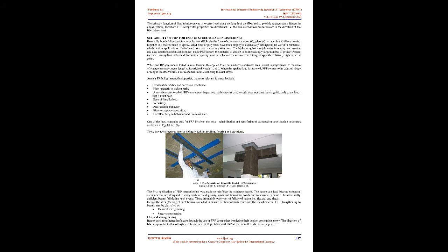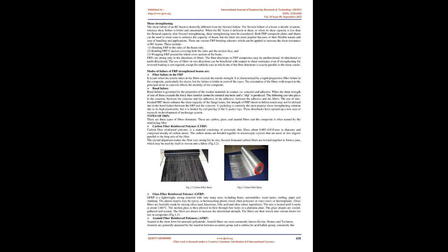Repair and rehabilitation work for concrete structures can broadly be classified into two categories. Repair, in which damage due to deterioration and cracking is corrected to restore the original structural shape, and strengthening, which is necessary to strengthen the structural capacity of members whose load-carrying capacity is either inadequate or whose strength has been severely impaired due to sustained damage.